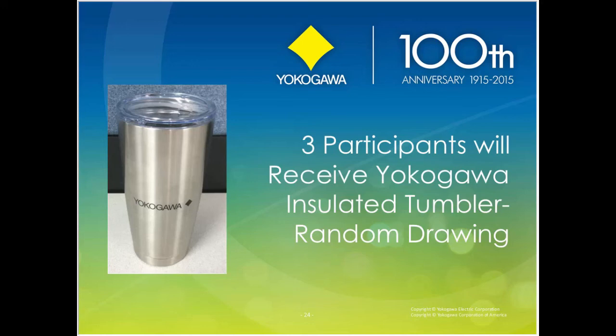Yeah, it's more of an issue of lag as it comes up to the temperature of the process, and as the process continues to drift in temperature, for the thermal well to chase it. So it's not per se an accuracy issue, it's just the time delay.